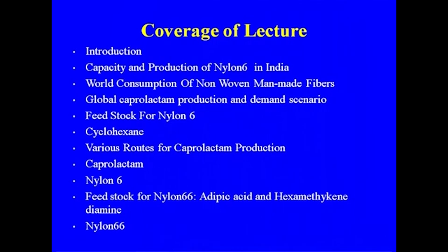material which comes from benzene, and so we will detail the process flow diagram for cyclohexane manufacturing and the various routes of caprolactam, because a number of routes are available for making caprolactam, but cyclohexane remains one of the important feedstocks. Other routes are from toluene to benzoic acid and others, but the major route is from cyclohexane, and through the final Beckmann rearrangement of the reaction.